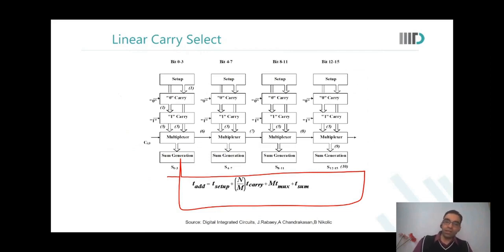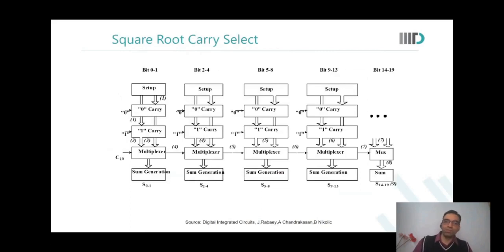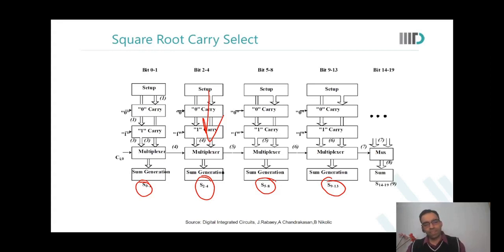However, another interesting way is you say that, okay, over here there are only 2 bits. Over here there are 3 bits. Over here there are 4 bits, and so on. So I'm gradually increasing the total number of bits that this system is taking up. Why am I doing that? Why am I increasing the bits? Is it the concept of logical effort? At the end stages near the output, we increase the size so that we get the optimal delay.